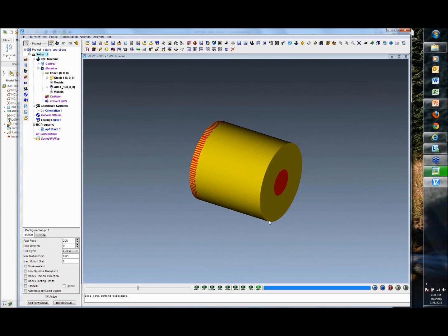I've seen setups where they have machines built into this and simulate the machines and look for tool crashing. You can also do that with Pro-E too. You can do machine crashing with Pro-E with Mechanism. I've seen that as well. But Vericut is a bigger tool, and what Pro-E buys is purely basically to run the CL file.